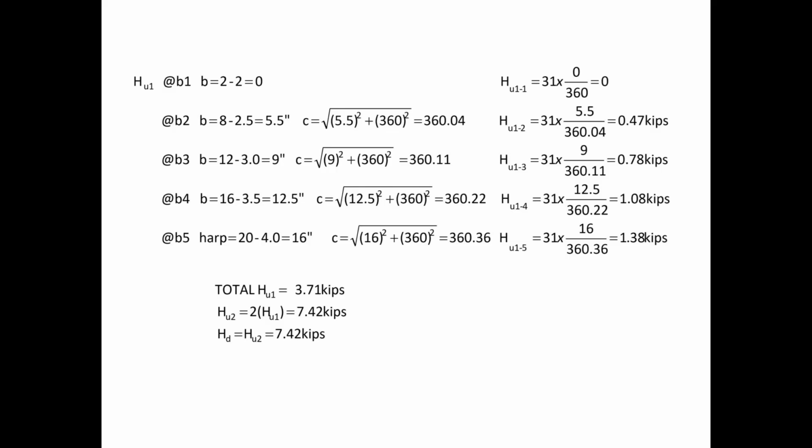You may have just answered your next question, but I'm going to say it anyway. Where is the number 2.5, etc., coming from on line B2? Yep, so that's coming from section AA. If you look at section AA, you can see that strand 1 is at 2 inches, and then each subsequent strand is a 1/2 inch above the previous strand.